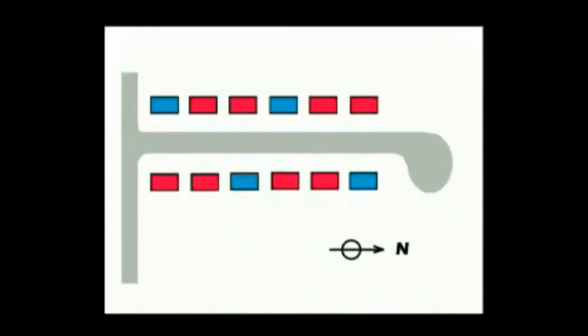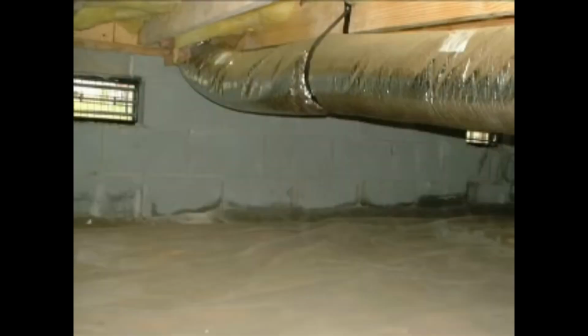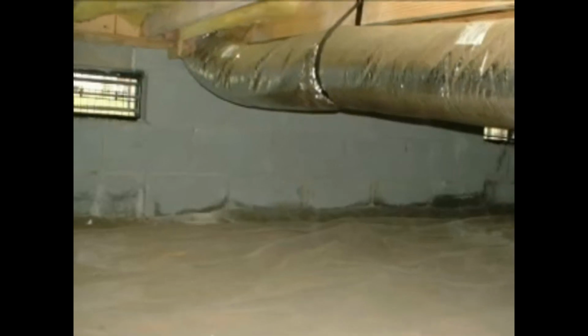Looking at this site plan, you can readily see how the experiment was set up. The 4 houses are the control group. The control homes are wall-vented crawl spaces with the foundation vents left open all the time. And be sure to notice how 100% of the earth floor in these crawl spaces is fully covered with a ground vapor retarder of 6 mil polyethylene.